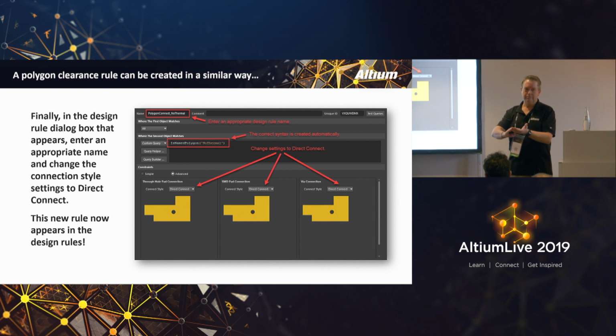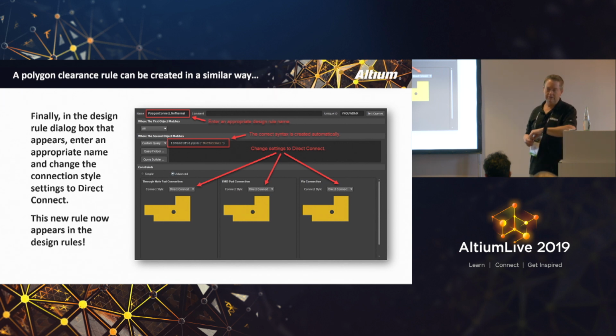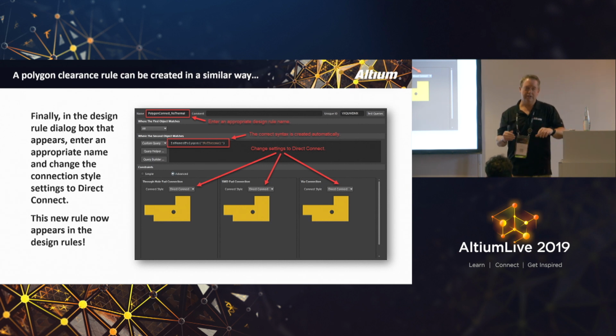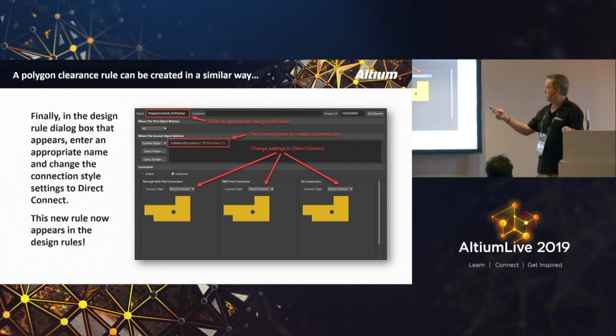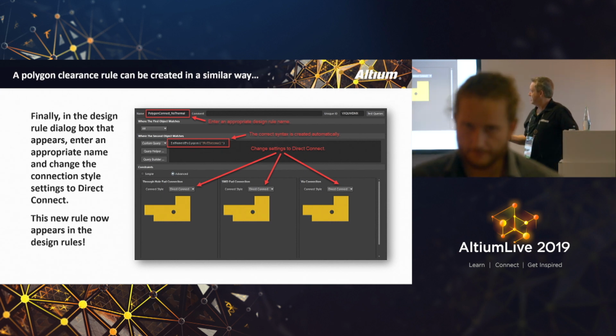And your last catch-all rule is going to be what happens by default if there's no name or other requirements for that particular element: clearance, thermal, or clearance, polygon, otherwise. Because I want thermal relief pads on everything by default, my exception is going to be a no thermal rule, and that's why I did it that way.